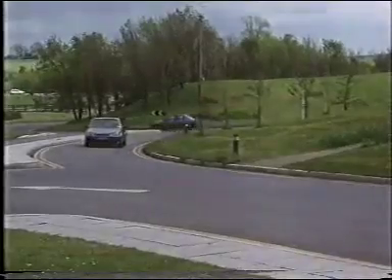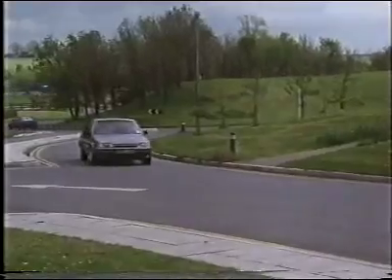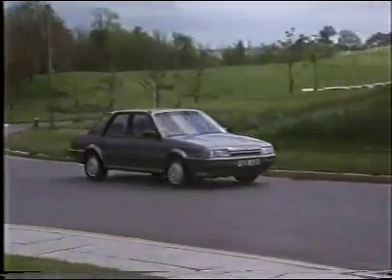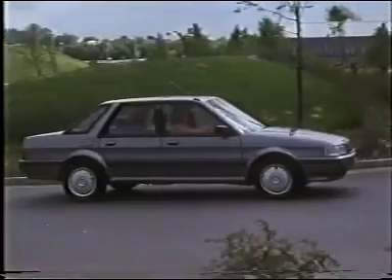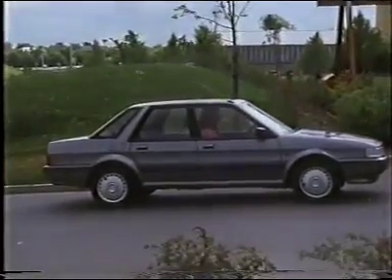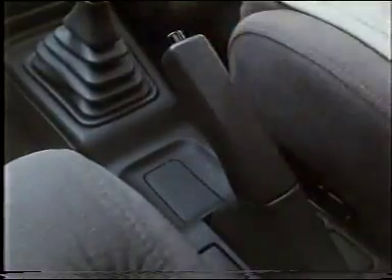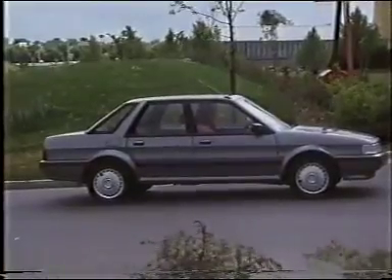Now let's look at a real engineering example. One of the tests applied to new cars is to drive up and down a steep hill. Stopping and starting tests the ability of the foot brake and the handbrake. Let's try to work out the force that must be resisted by the handbrake when a car is parked on a steep hill. To do that, I'll draw the free body diagram of the whole car. Although the car is a complex collection of components, including a driver, it's perfectly valid to choose the whole car as a free body.